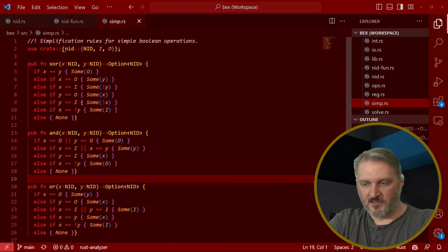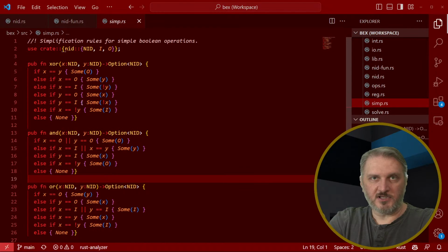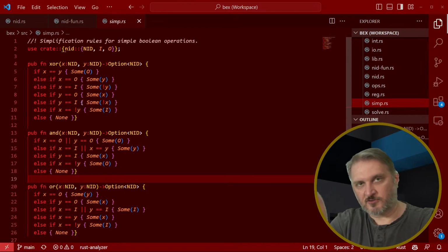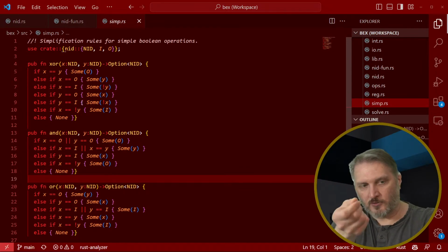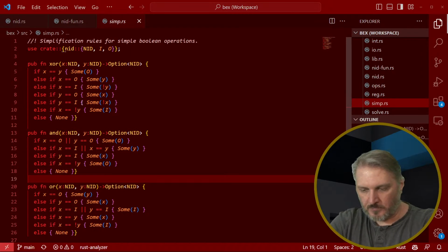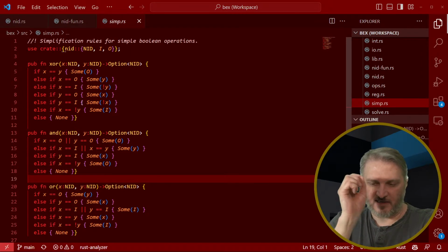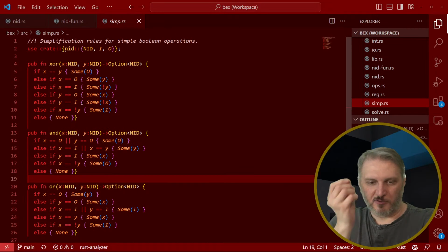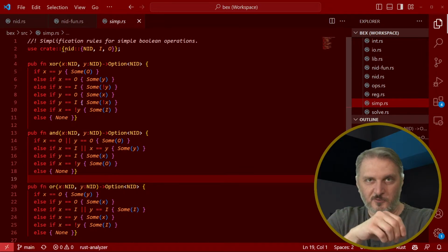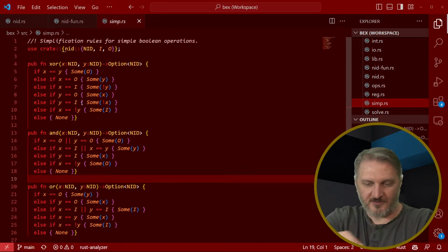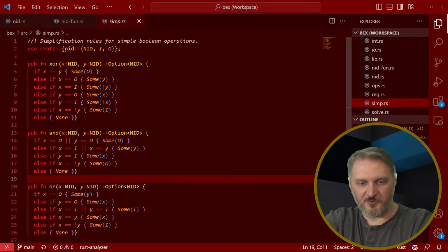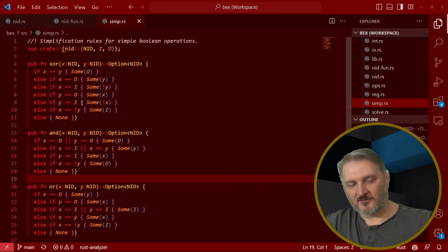So if the inputs were called A and B, and you pass them both X, then you can just replace them both with A, and now you only have input A. And if you pass in X and not X, then you leave A alone, and B you replace with not A, and then you rewrite the function that way.